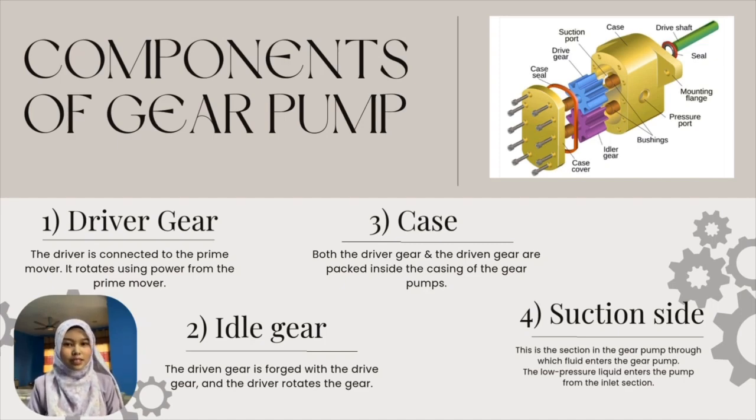The third one is case. The case houses both the driver gear and the idle gear. It ensures that the gears are properly enclosed and aligned for efficient operation. The case also prevents fluid leakage and directs the flow of liquid through the pump.